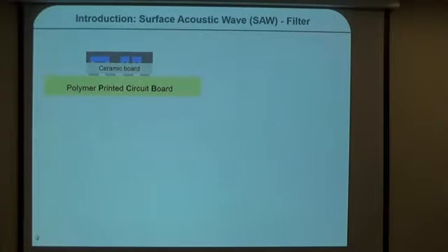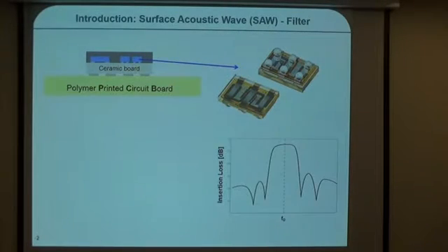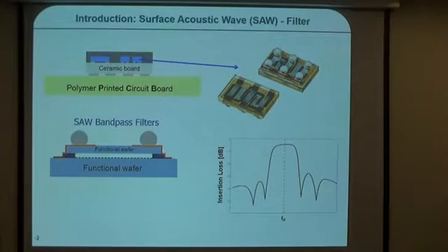And one type of functional components could be the surface acoustic wave filter in smartphones. What they basically do is to filter out one frequency within a certain bandwidth and suppress all other frequencies. In modern smartphones, in the next generation, there will be up to 100 of these surface acoustic wave filters in one single phone. And if we have a look on the cross-section of those filters, we can see that they mainly consist of a functional wave.